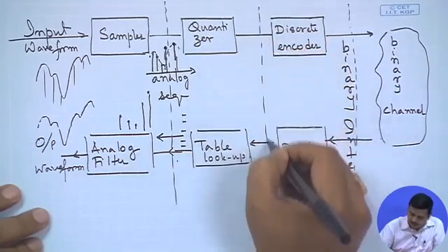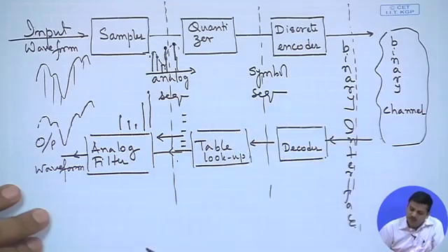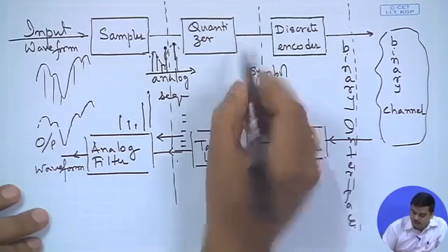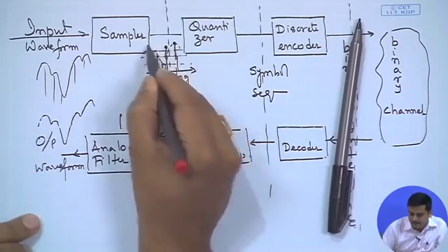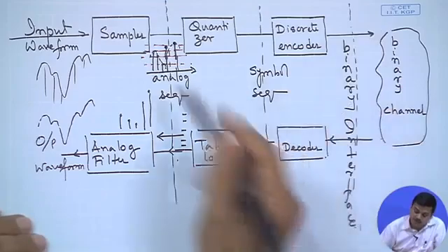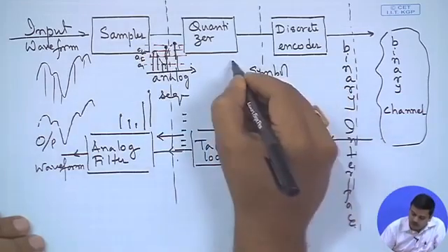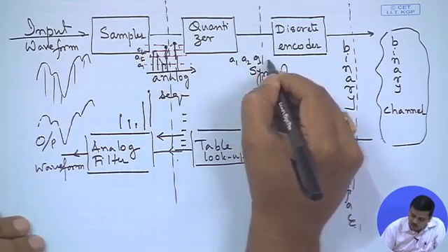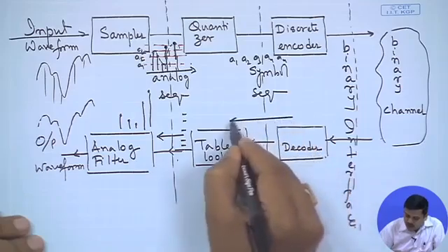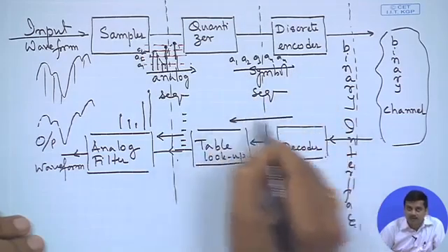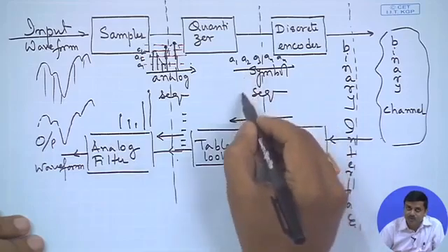And if I look at here, what we are going to get is a symbol sequence. Why is it so? Because these will be passed through a quantizer. A quantizer would mean that you are having different levels. So, each level could be assigned a particular symbol. This could be, let us say, A1, A2 or A, B, C, D, A3 and so on. So, what is going out is basically a sequence of A1, A2, A3, maybe A4, A4 and so on and so forth. The decoder is similarly going to give such sequences or levels which were there. Those sequences would be converted to signal levels and would be sent out. So, this is a symbol sequence.